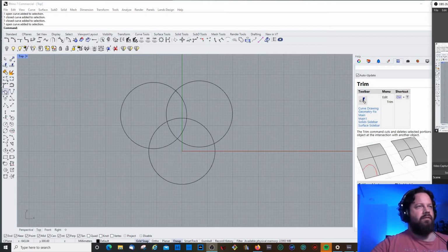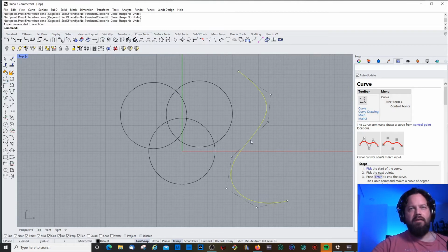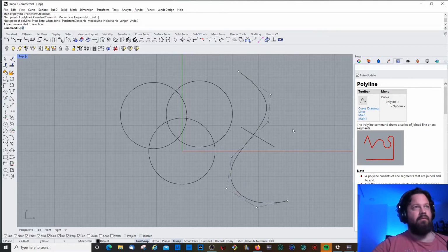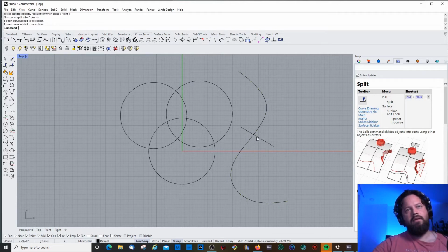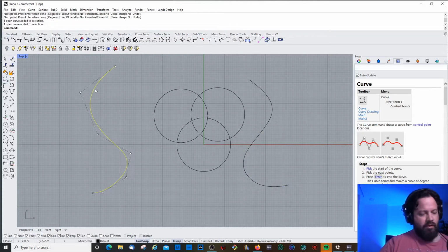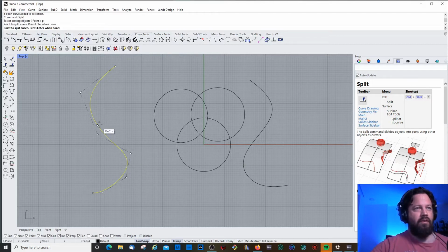Another very useful tool is split at a point. So for example, you have this and I want to split it on a certain point. In the past, what I did was drawing a line here and then say split, object to split, and then selecting the line. That's one way, but a much faster way is actually to use the subcommand. When you type split, you can see here, either you type P or you can also click there. I haven't mentioned it before, but you can also click here. If you are a clicker, then you can click here. I like to press P, and then you can choose a point on your curve, enter, and that splits your curve as well. That's much faster, and I should use it way more often, but sometimes I just forget.